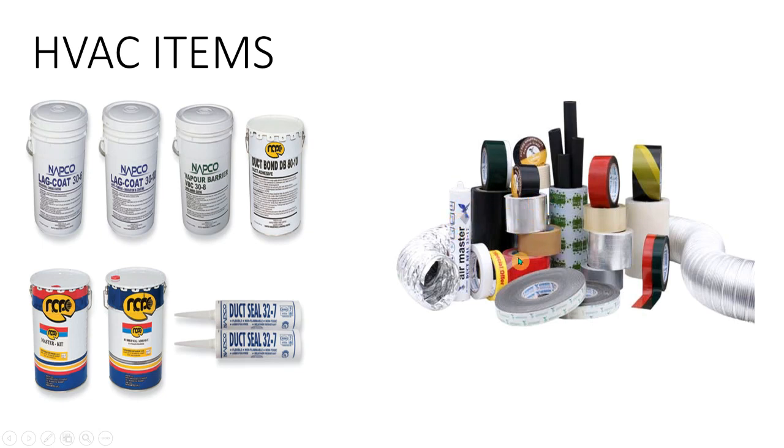Then we have duct tape. Once you put the insulation over the duct or around the duct, you will use the duct tape for the tightening purpose, so that the insulation will be completely stuck to the duct. Then after that we have duct coating, which we will be using for the vapor protection. We will be using another material called canvas cloth, but in some cases that's not mandatory. Again, it depends on your project requirement.